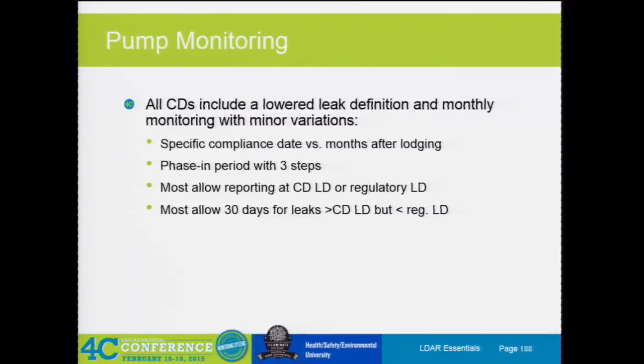So you don't need to tell operations and maintenance that, but it may be your pump, you don't have a backup pump and it's leaking and you're going to bring down the process unit or something like that, or hey, I got to order this part and then I can switch over to my pump B, but I can't do that right now because pump B's out and A's running. So if that's the case, then maybe you do have 30 days because it didn't trigger a federal leak definition. So you don't need to have everybody worrying about it. You know, the LDAR people can know, okay, this is really a 30-day leaker. But I'm still going to keep pushing maintenance and operations to get this done in the time frame of the 15 days. But you wouldn't have to report that if it was an issue. Does that make sense?